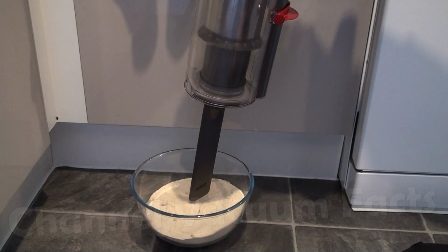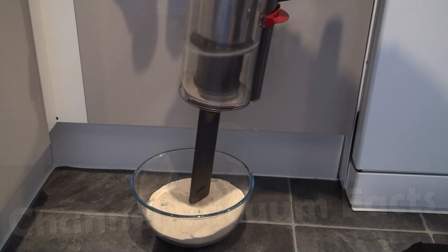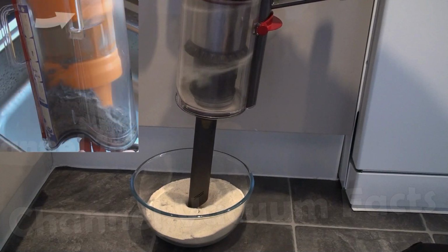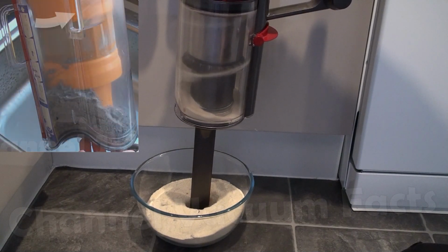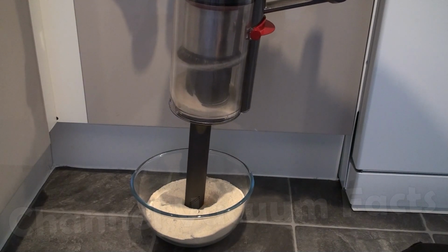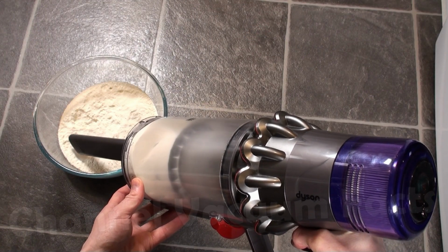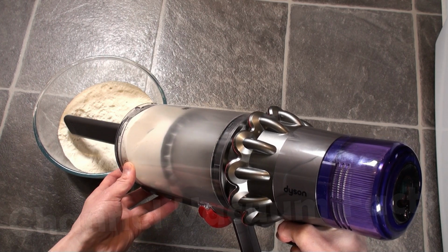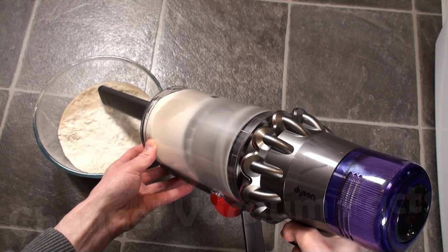Cyclonic dirt separation systems typically employ a pre-cyclonic filtration process in the bin. Dirt-laden air entering the bin is jetted utilising the Venturi effect, with the narrowing of the passage to increase speed, and cyclonically spins inside the bin. This is a large initial cyclone, causing dirt to be centrifuged and dropped to the bottom. This filters the largest of dirt particles.